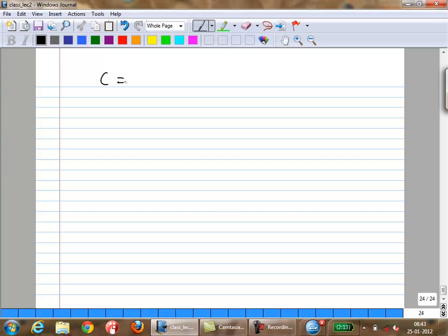If you express the overall capacitance in terms of the actual parallel plate capacitance and the fringing capacitance, you have some capacitance per unit area, let's call that C area, times L times W. That is your parallel plate capacitance, the ideal capacitance.